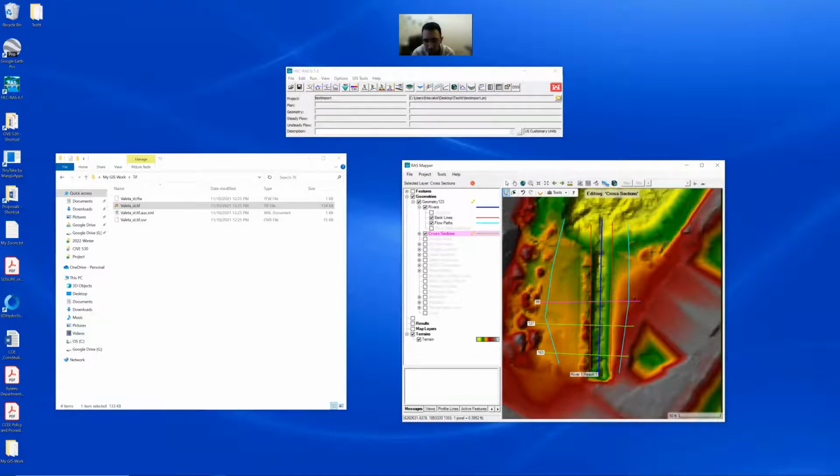So you want as many as that makes sense. Make sure that the lines that you draw are perpendicular to your river line. That's the whole purpose. So I'm going to add one more here, and last one when I'm entering the pond. Like this. So you're all set. Save your geometry again. Stop editing. Yes, you want to save it? The answer is yes. Now you have a geometry.